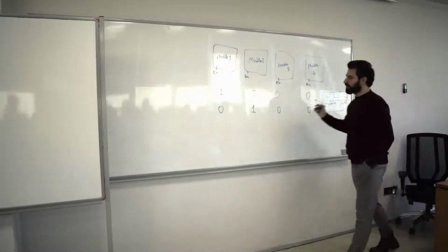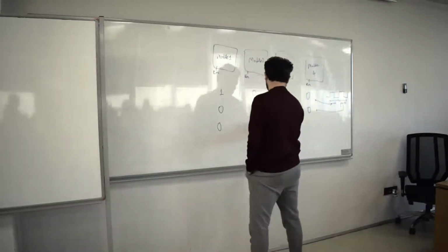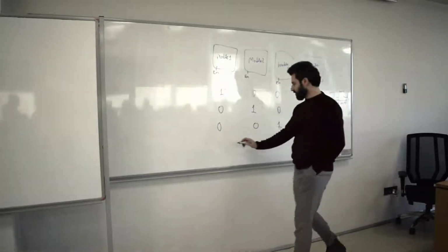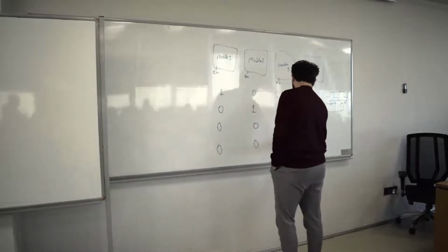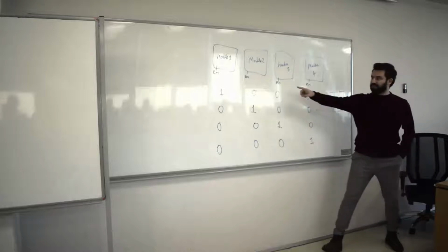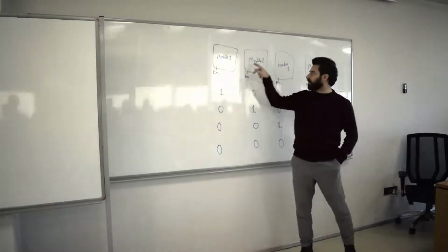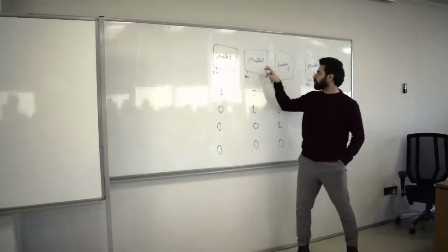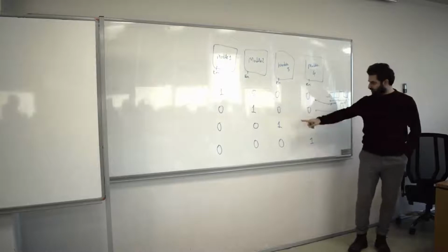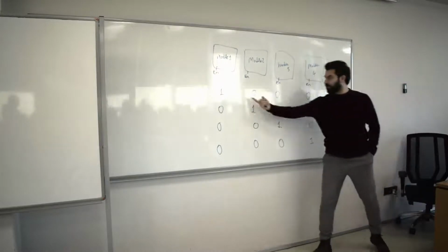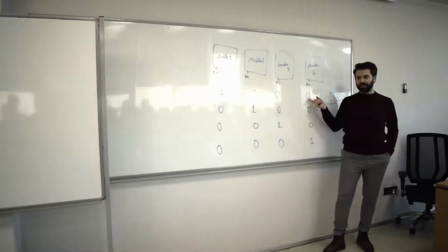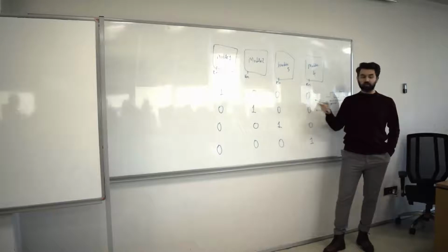In the next period, as you can guess, you disable this one, enable this one, and disable this one. Finally, you disable module 1, module 2, module 3, and enable module 4. That basically is just like counting, right? Module 1, 2, 3, 4, and then back to 1, 2, 3, 4. If you continue that, you actually complete the period, by the way. The period of this sequence is 4, because as you can see, this is the first output of that circuit, and then the counter. This is called a ring counter, by the way.